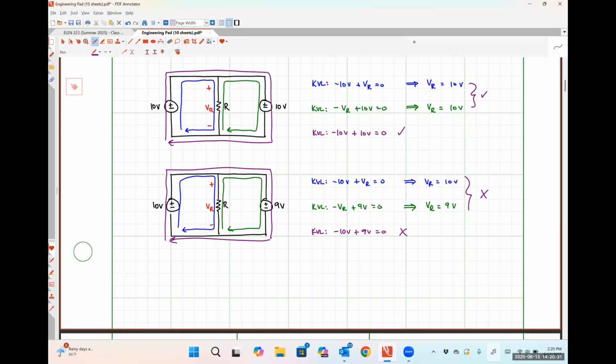And they utilize not only wires with a pretty decent resistance and a decent amount of insulation, but they also use controllers and things like that to help balance the voltages across each photocell so that they don't wind up starting fires, causing sparks and all of that kind of stuff to happen as well. Okay. For what it's worth, another place where you guys, particularly those of you that go work in the electrical utility industry after you graduate, might see voltage sources connected in parallel would be battery energy storage systems.